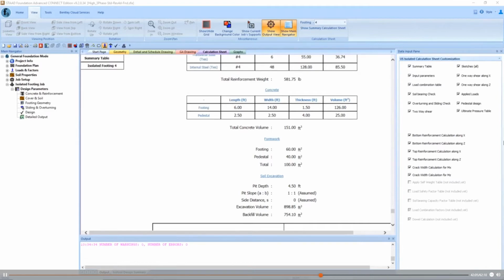So that's our passive earth pressure. We can actually use that passive earth pressure to optimize our foundation if we consider that pressure in our design calculation. Previously, we didn't have the ability to consider that passive earth pressure in our design calculation. So we only relied on the cohesion and our resistance from the soil friction.